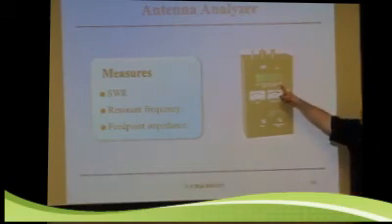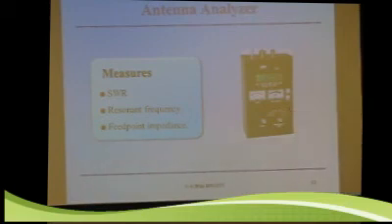An antenna analyzer is another great device that has just recently become cost effective for people. This is an MFJ one here. It measures the SWR, but you can actually use it to plot what we were just showing you before, the SWR curve for the 80 meter antenna. This one reads out the data and you can plot it yourself. Now they have some with little graphic screens where they plot it for you.